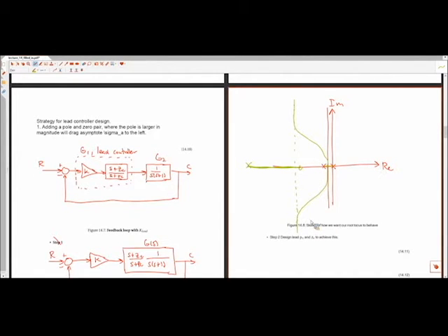I don't know if you were here on Monday, but there was a discussion that proportional derivative controllers don't technically exist. You can't actually build one. Every single proportional derivative controller is a filtered proportional derivative controller, and that's exactly a lead controller. So we use the term proportional derivative because that's really intuitive and that's what the industry calls it, but it's a little bit of a lie. It's not technically a proportional derivative controller. So now we're saying, let's unmask that idea of there being a filtered derivative, and look at moving the poles and zeros around and use the full thing. If that makes sense. Yeah. So it'd be like a PD controller essentially.